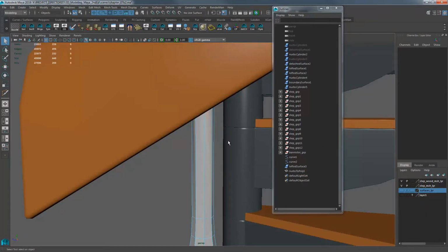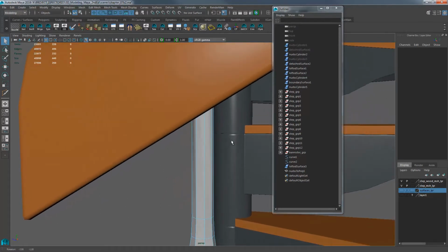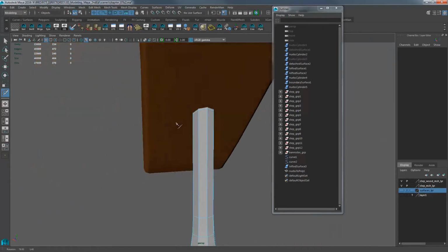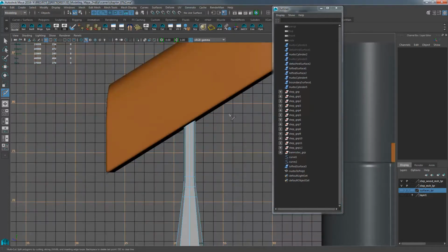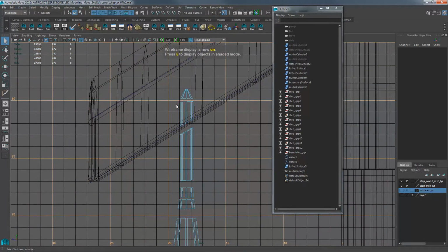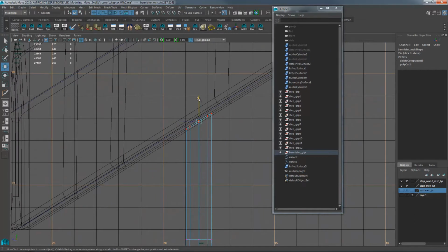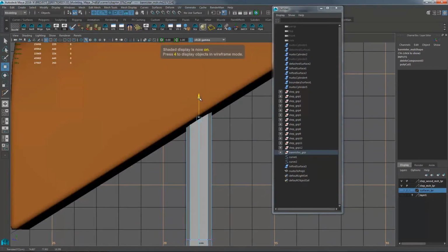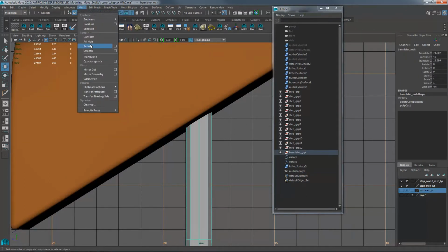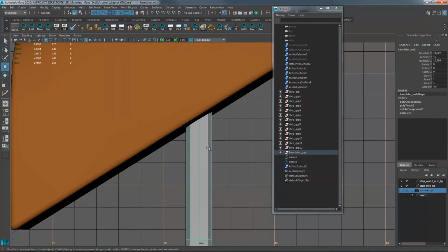And I'm going to make this cut in the 3D view. So I'm just going to rotate the camera until I get to that right angle, then perform the cut. There it is. Got it. Switch back to the right-hand view. Back to faces. Delete those. Take these faces, just tuck them up just ever so slightly, so they're just tucked right there into the surface. Cap the end, full hole, and then bevel work.